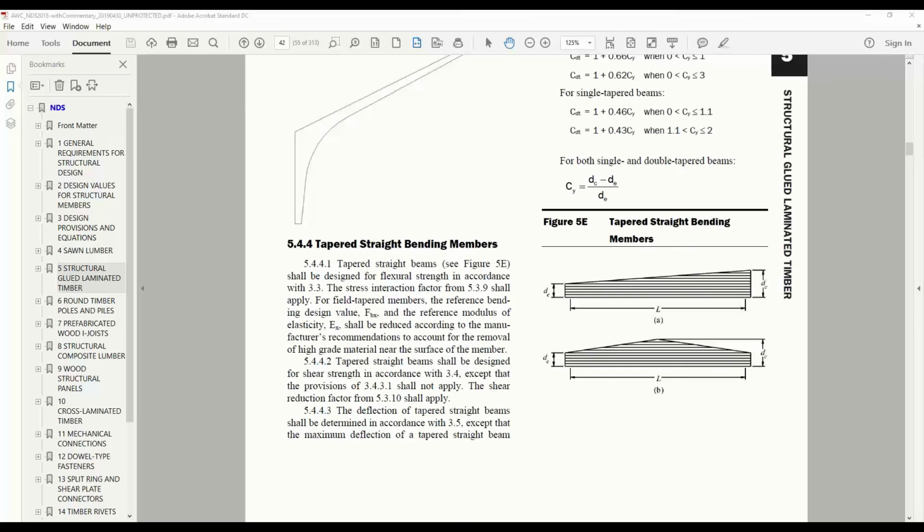No, I don't. But there are requirements that are geared towards the fire resistance of the adhesive, so the member is not going to delaminate when exposed to a fire. The char front would propagate through that adhesive line the same as it would if it were solid wood. So the presence of that adhesive does not have any impact on the char rate of the member.